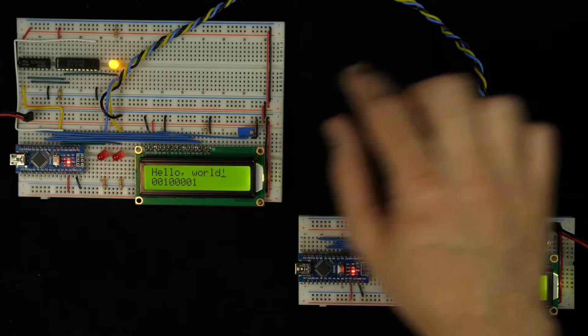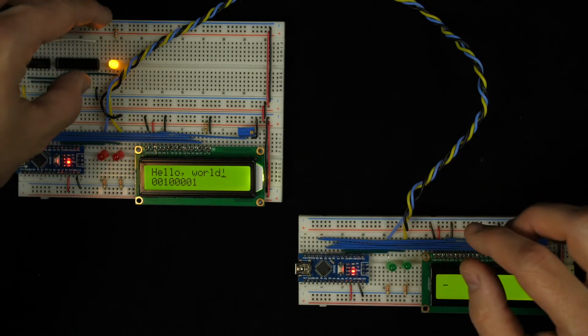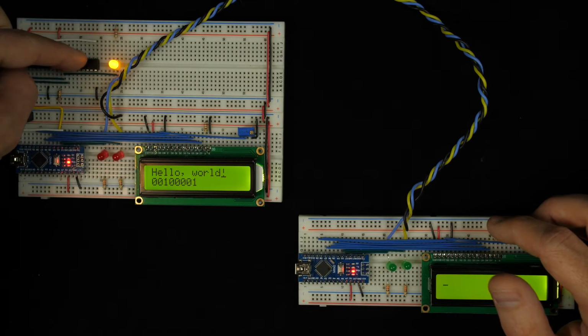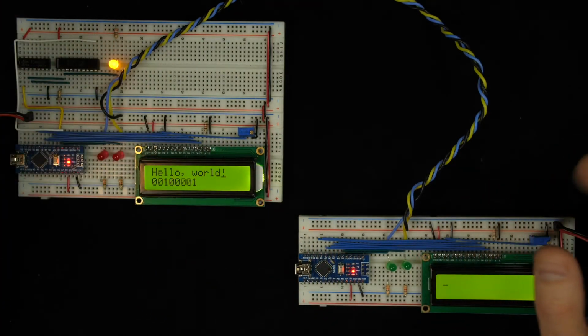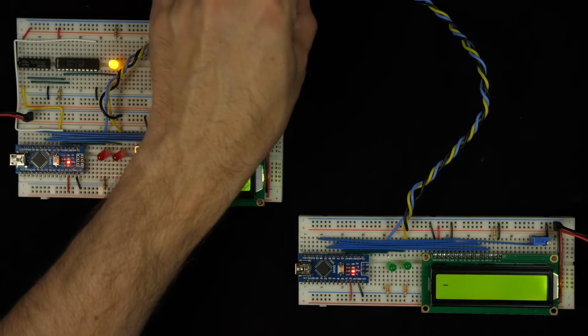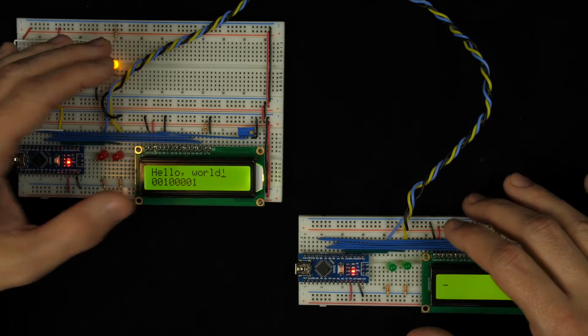Now, to help us detect if there was an error sending the message, we could do the same thing on the receiver side. In other words, we could duplicate essentially this same circuit over here on the receiver, and then we'd be computing the parity of the sent message and computing the parity of the received message. And then if any single bit gets flipped, 0 changes to a 1 or 1 changes to a 0, between the transmitter and receiver, possibly due to this evil little button I've installed here, then the parity won't match and we'll know that there was an error.